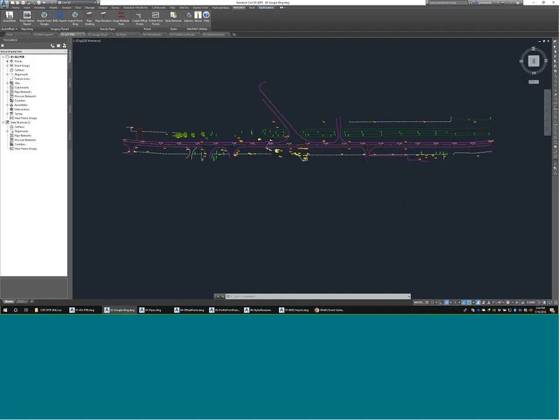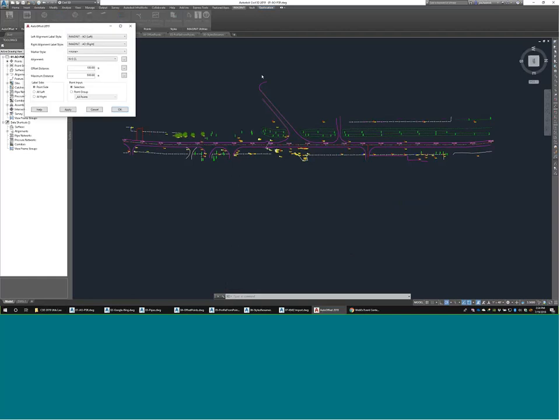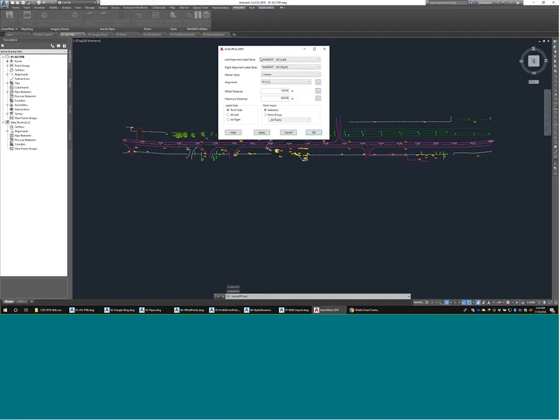All right, so we'll move back to auto offset and the point stakeout report. And we're still looking at that exact same drawing, same area. It happens to be in Florida, as where this drawing came from. And the way auto offset works is, I'll pull this over to the screen. Essentially, you need to give it some style information. So what styles do we want to use for the left alignment side, for the right alignment label?